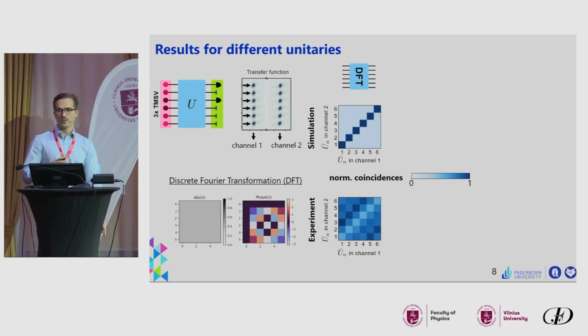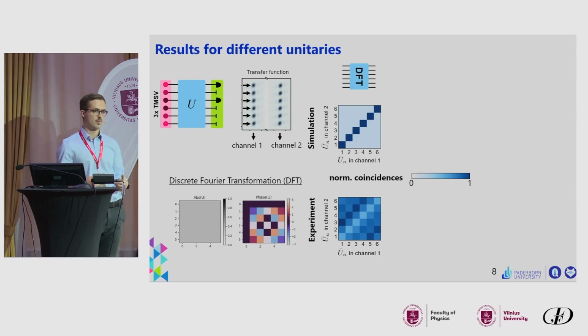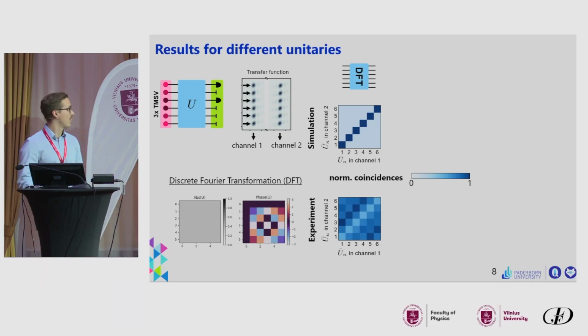Why? Because we had a lot of spectral phases in our system, and this basically adds another set of random phases on this transfer function, which messes up the phase relations. So we have to come up with a phase compensation algorithm, which scans every bin against each other bin to set all the phase relations properly. And if we do that, it works.